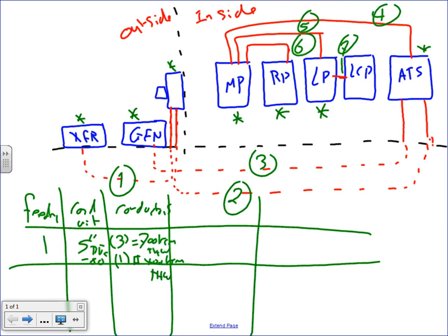So the conductor size. So at least minimum the feeder number and the conductor and the conduit size, guys. I like to see the overcurrent protection device at the end of it. That will be a 500 amp. And notes. If you have any notes, you can write notes, anything you want to do. That's at least. At least.